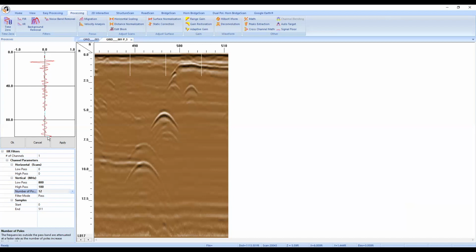I'm looking at the scan briefly just to see if I can see any moments where the scan wiggles back and forth and remains on the left or right-hand side. If you notice anything like that in your scan here, you can click and drag to update it too, just to make sure that everything's okay. And if you see any moments where it's acting funny, like right over here, and a little bit up here too, that could be indicative of low frequency interference affecting the wave. And you can help take care of that with a higher high pass filter value. So we'll try 150 just to see if that cleans it up.